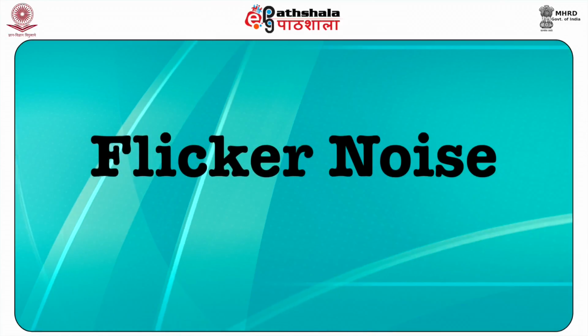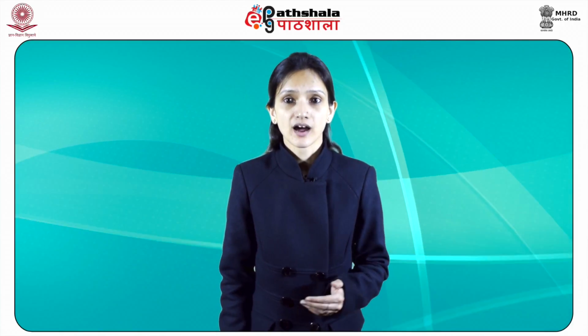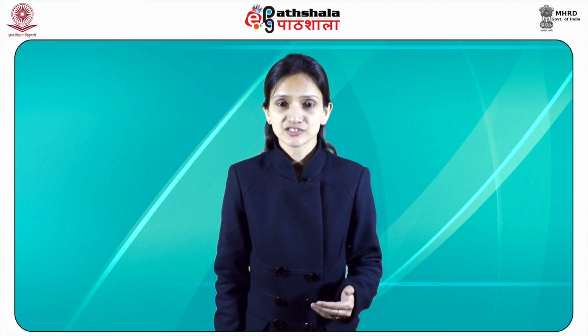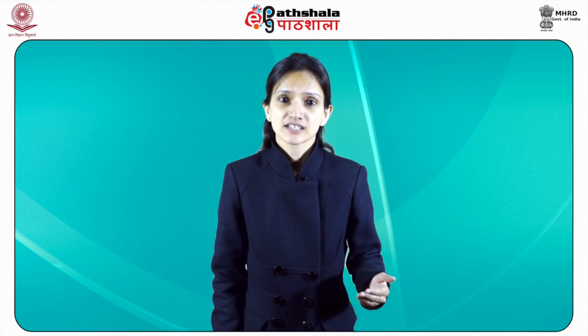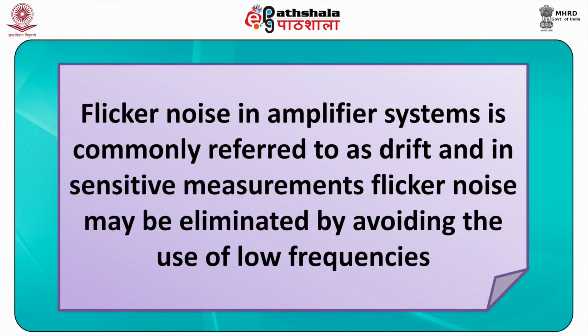Next is flicker noise. The third kind of fundamental noise, flicker noise, is observed for low frequency signals. The physical origins of this noise are not well understood, although all solid-state devices are subject to flicker noise. Field effect transistors, that is FETs, seem to be affected less than bipolar devices. Flicker noise in amplifier systems is commonly referred to as drift. In sensitive measurements, flicker noise may be eliminated by avoiding the use of low frequencies.